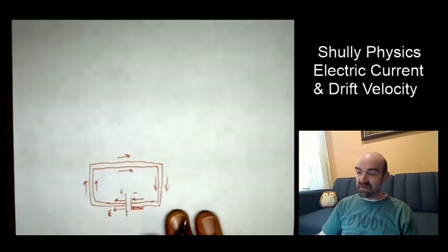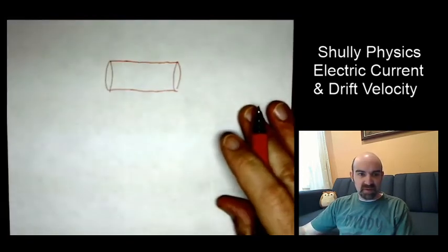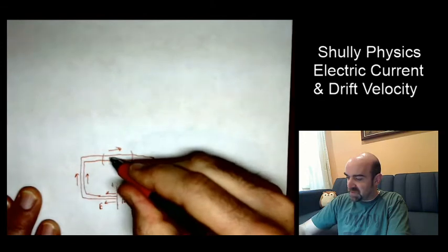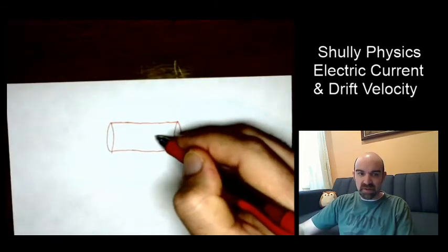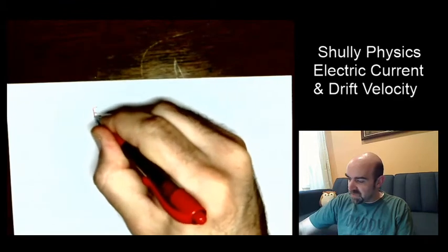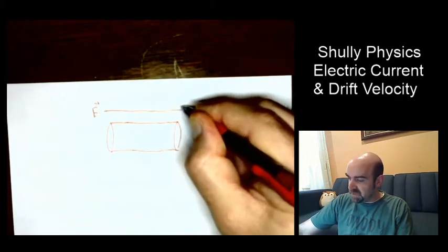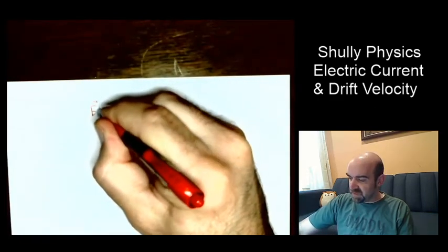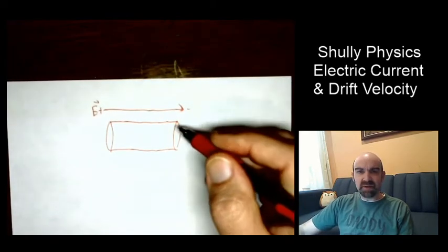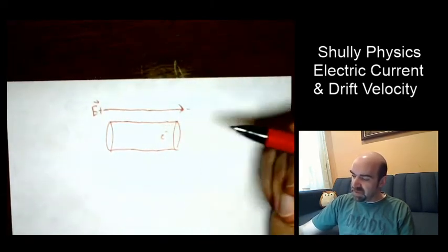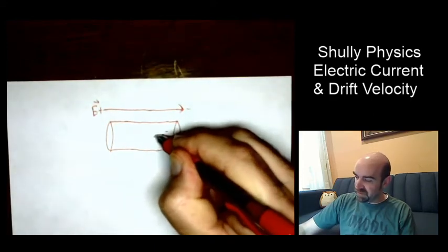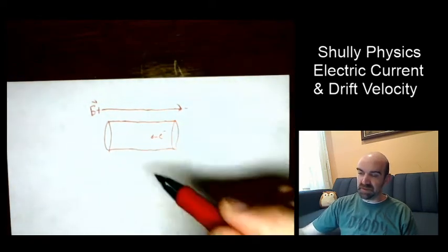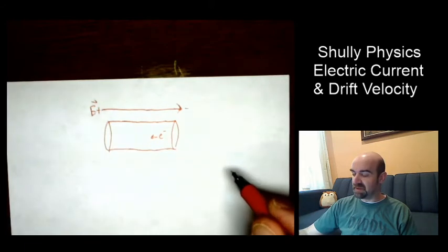Now the electric field is going to be applied to our zoom in on a segment of this circuit. We can see how we're going to just take a little segment of this conducting material here and focus on it. So the electric field is applied from left towards the right in this scenario. Think of it like a positive side and a negative side. So if we did have an electron in here, it would be attracted to the left as the electric field is applied to the right. So there's going to be this drift of electrons progressing through this segment of the conductor.